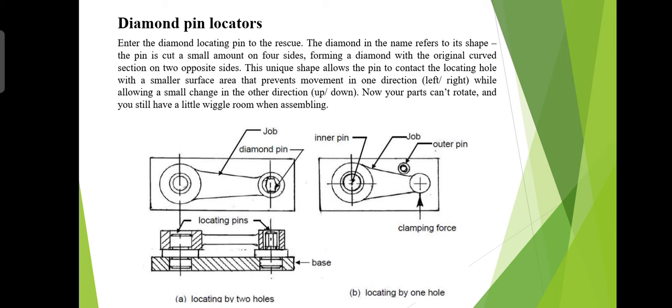and similarly the distance between points A and B, if these are the points, this one is the A and this one is the B, in a jig or fixture has a tolerance capital Y. Now if the workpiece is effectively located on pin capital A, the allowance between pin capital B and hole capital B will be X plus Y. Extreme cases occur when both hole and pin center to center dimensions are at maximum or minimum condition. Due to this, there will be large allowances between the hole and pin capital B in the y direction.